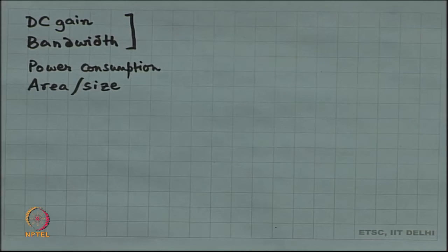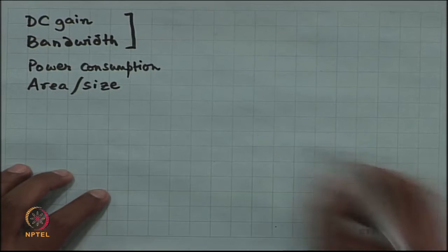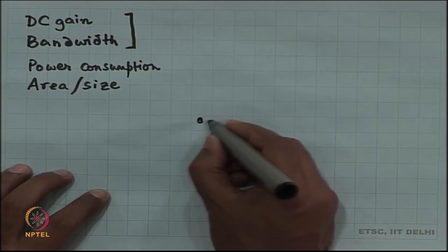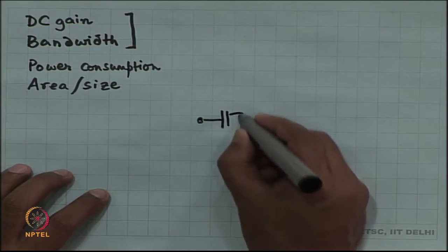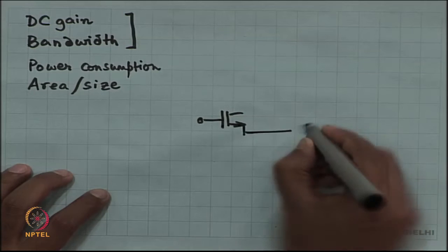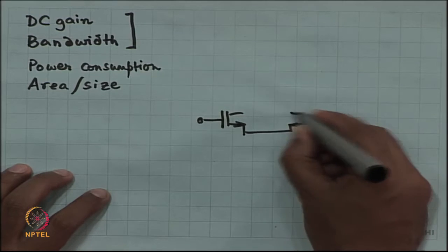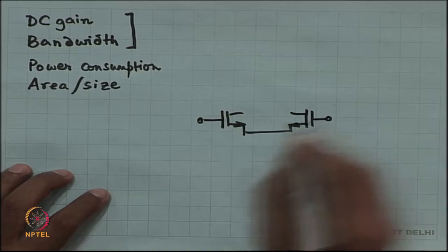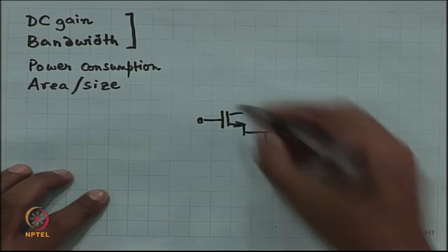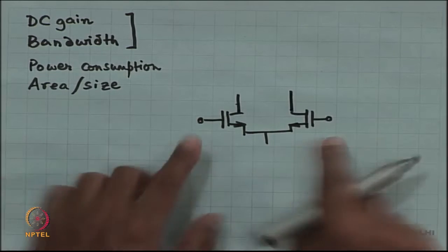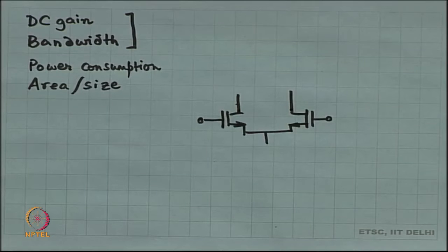All right. What is going to be the structure of our op amp? You probably will have, let us take one of the simplest cases. It is going to start with a differential pair. This is the input structure, a differential pair, and usually when you have a differential pair, you will have to have a tail current source.